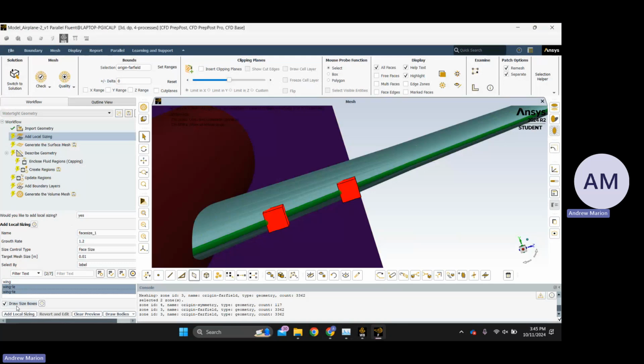If you were doing this manually yourself and building the domain, once you've subtracted it and gotten your domain and everything set up, you would go in and click the leading edge, click the trailing edge, and name each section, each wall: leading edge, trailing edge, wing, aircraft, fluid. And Ansys will actually recognize that English. It's like, oh, you typed in fluid, this is a fluid domain, and it'll set up things for you. All right, we're going to click add local.